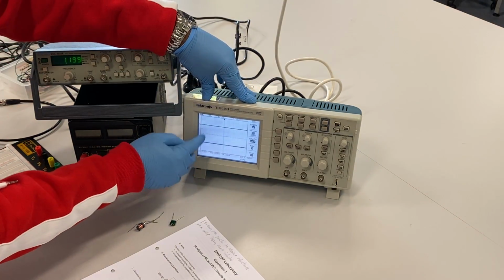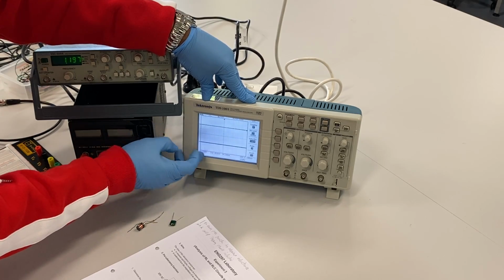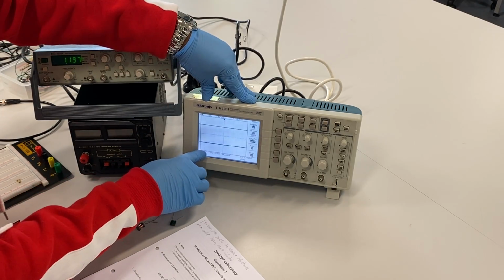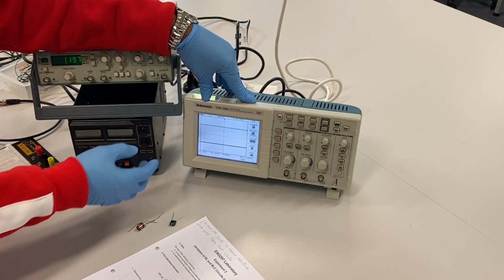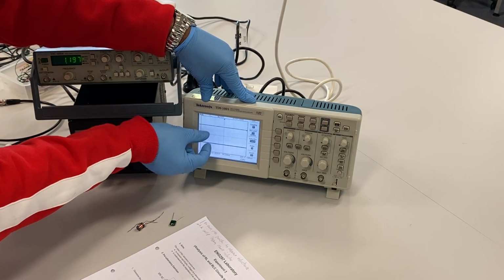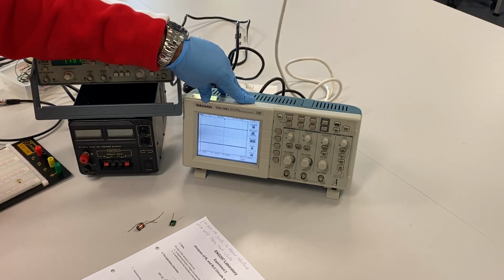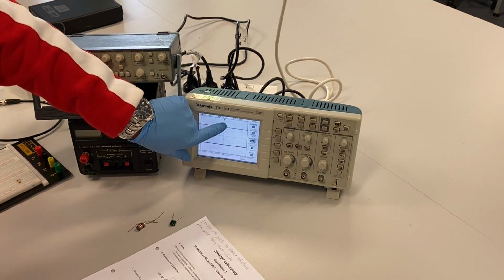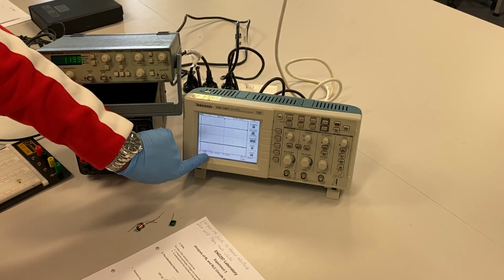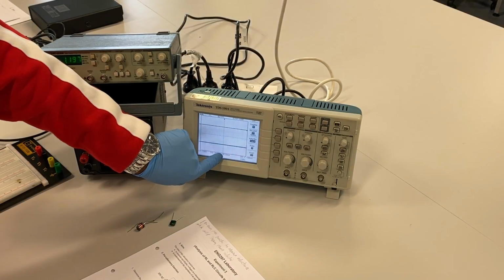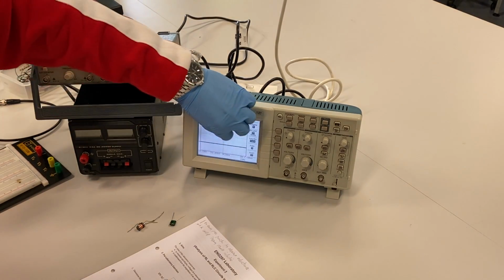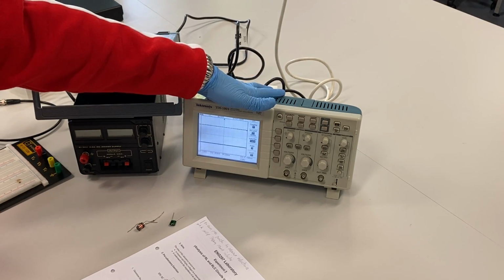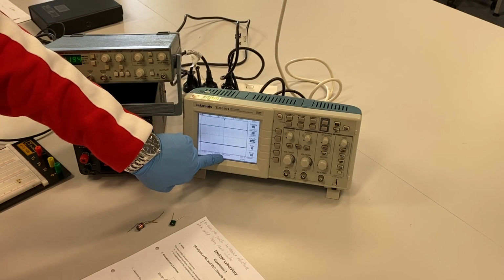Since they are boxes, each and every box is represented with what we call a channel division. In this one they wrote channel 1 5V. It means each small square in the y-axis represents 5 volts, right? So if your signal is covering 4 of those boxes, it means it is 20 volts peak to peak, in other words. Then the time division here is 2.5 milliseconds. It means 1 box right now, without any input signal, is represented by 2.5 milliseconds.